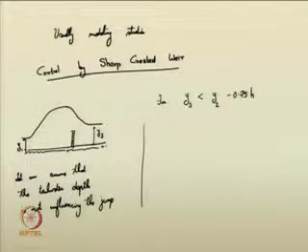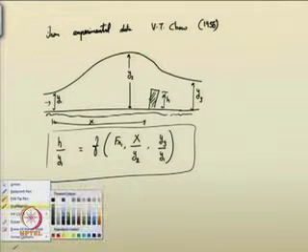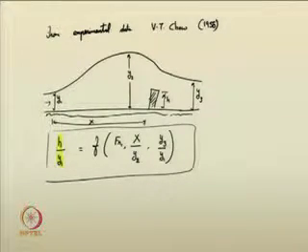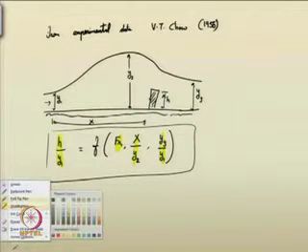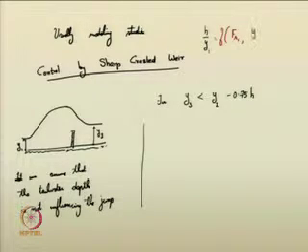So, if y3 is not influencing the situation, then as we suggested in the previous slide, h by y1 is a function of the Froude number, x by y2, and y3 by y1. Now, if y3 is not influencing the hydraulic jump, then we can easily suggest that h by y1 is some function of the Froude number and y2 by y1, because y3 is not influencing the situation.